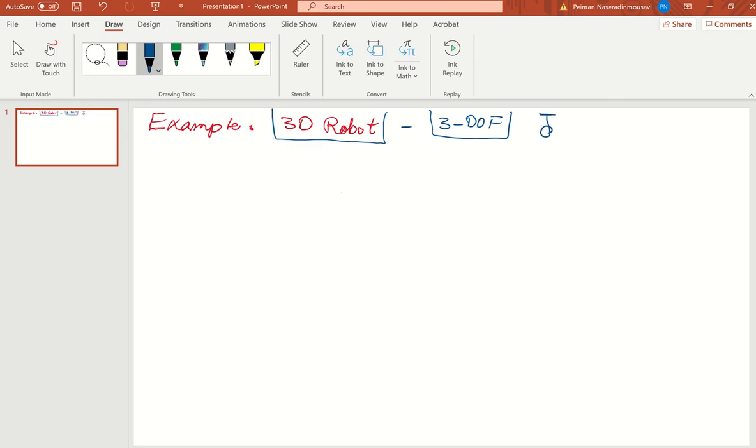And then after finding it analytically, I'm going to go to MATLAB and make a simulation of this robot by movie, and I'm going to plot x, y, z of the end effector, and then plot vx, vy and vz of this end effector. I'm going to plot omega x, omega y and omega z of this end effector through the Jacobian matrix. So it's going to be very comprehensive. This class and the next class, I think it's going to take 2 classes, is going to be a summary of whatever I have done until today.